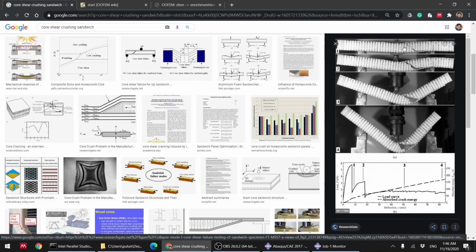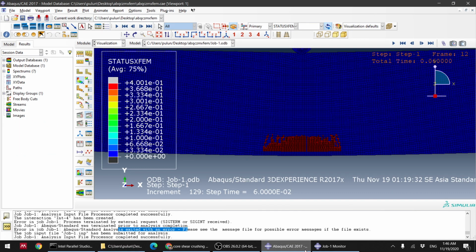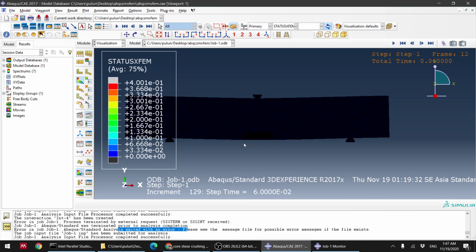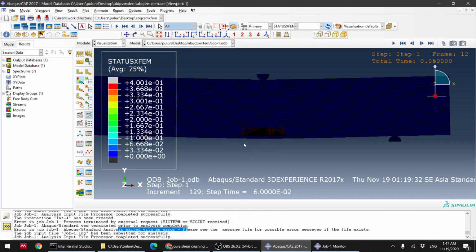they go here, they make this, how do you call it, the transverse crack, and then they will create another delamination here, because if you see here, it doesn't seem like that, right? So tomorrow we are going to modify the settings, for example making the pin larger or making the specimen thinner.